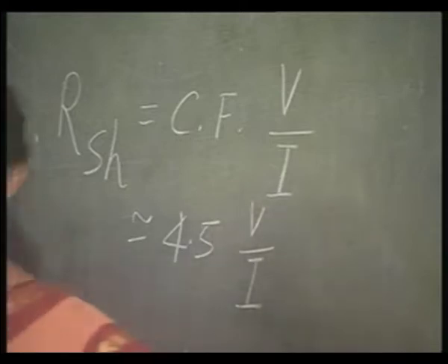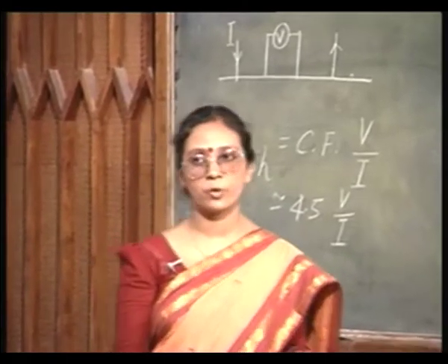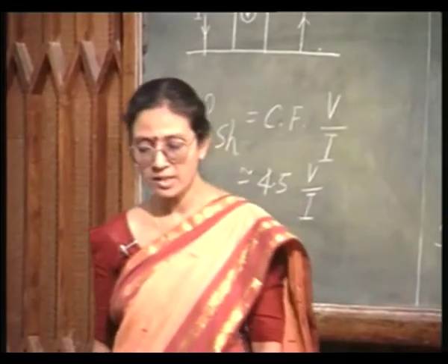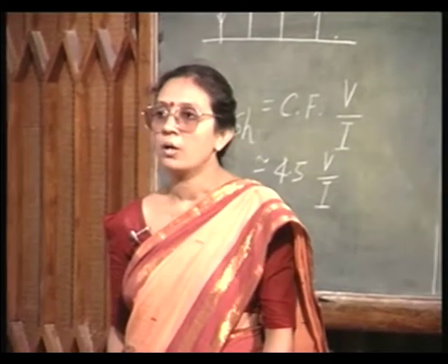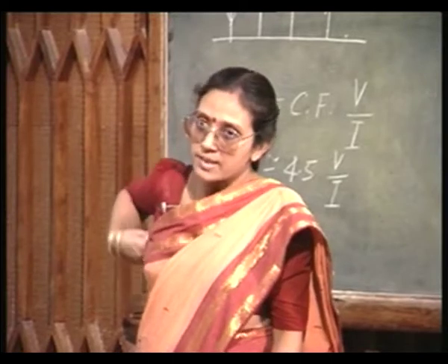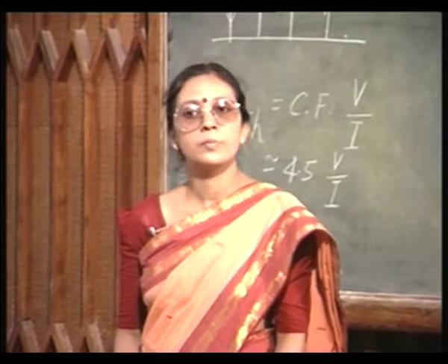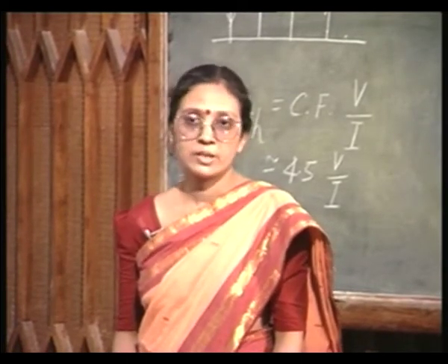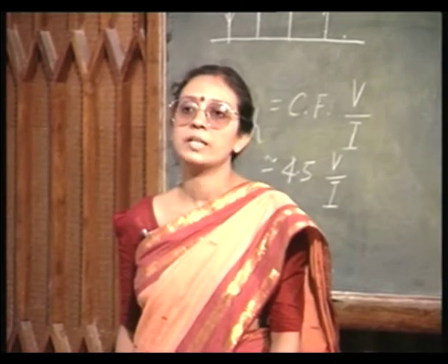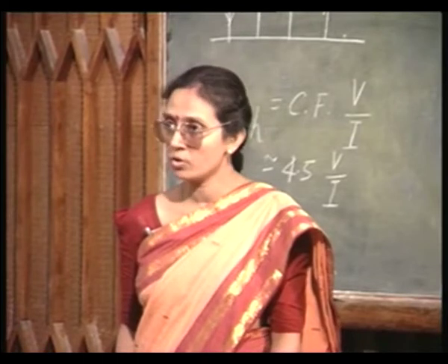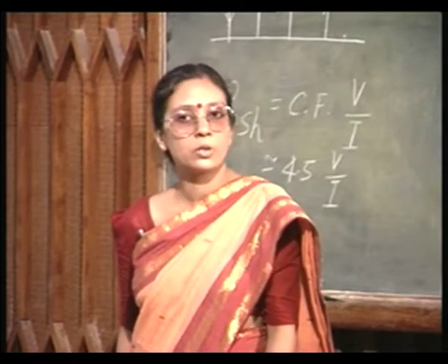So, you have found the sheet resistance, 4-point probe technique, it is a very common technique. Okay. Now, as I said, in most cases the sheet resistance will be a parameter. So, if at the end of the process you find that the sheet resistance conforms to your expected value, fine, you can go ahead.